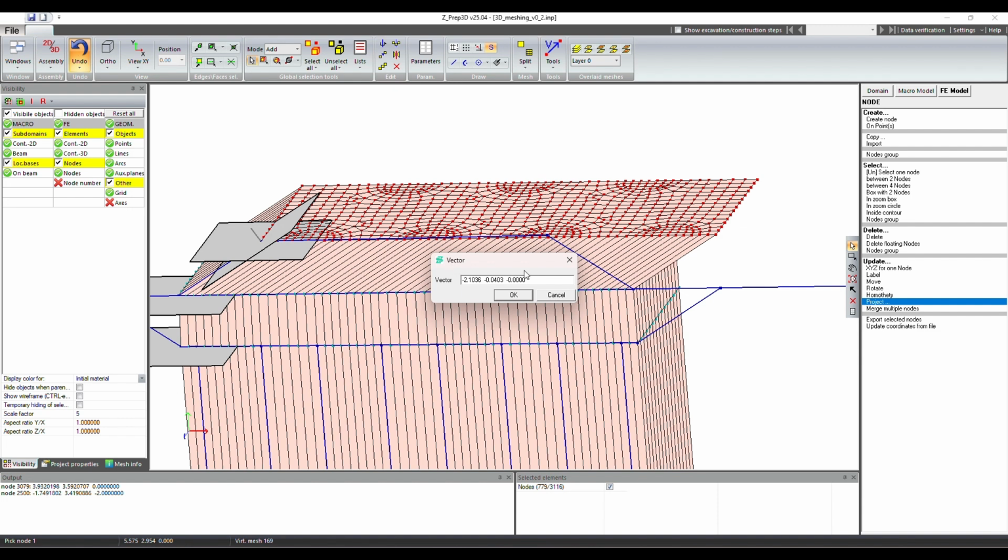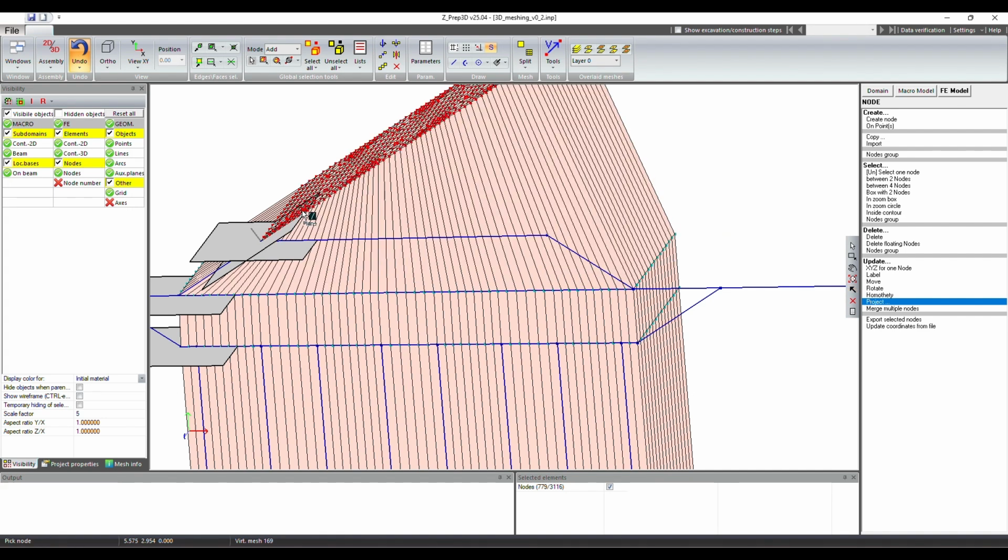So first we will project all the nodes on this plane here that is relatively steep, and we need to specify somehow an oblique angle. We will do, this is x, so we choose minus 1x, 1y, so it goes up diagonally up here, and we project on this plane.